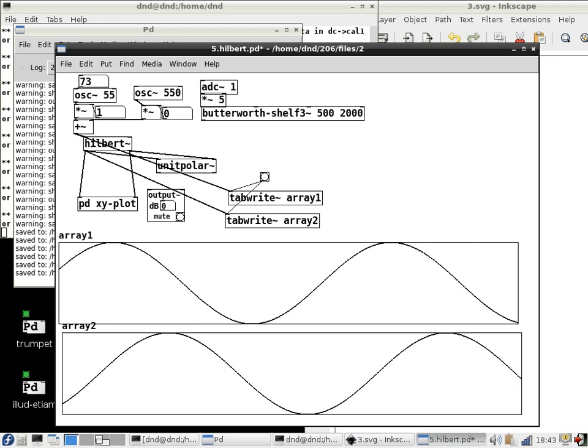At DC, at zero frequency, there's no phase to be in except for in phase, or 180 degrees out, but actually it's really in phase with a negative amplitude. And at very high frequencies, frequently the phase lags by 90 degrees times the number of poles in the filter or something like that. So you get an increasing phase lag as the frequency goes up.